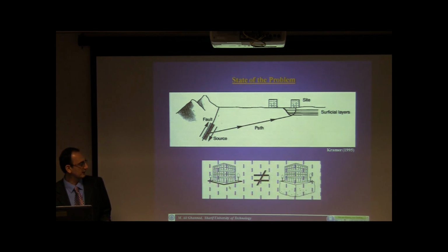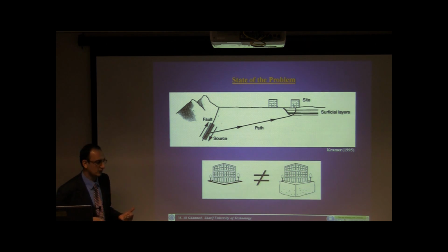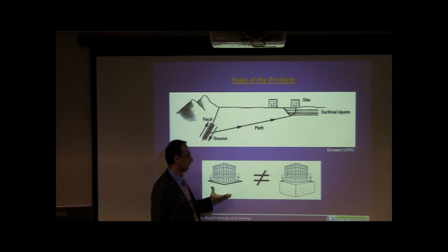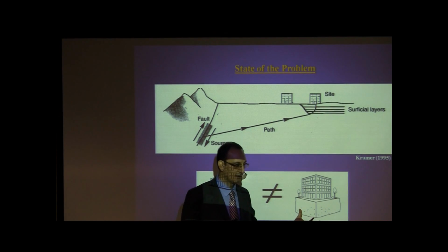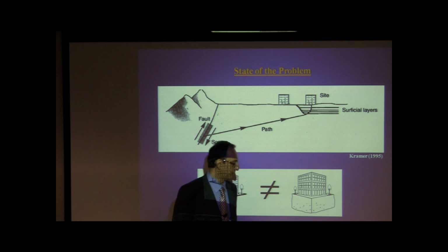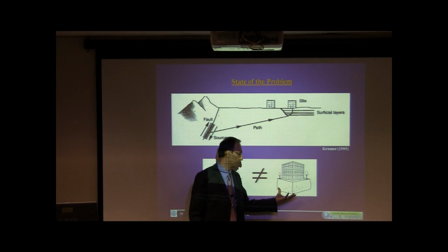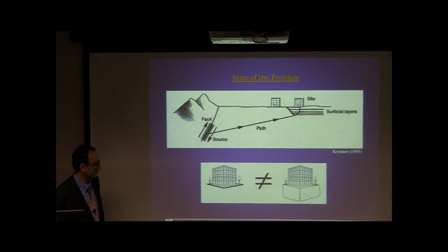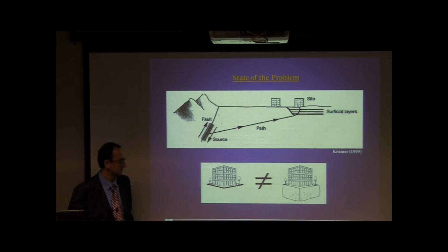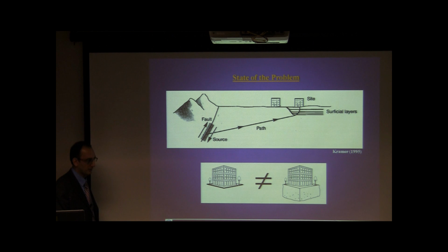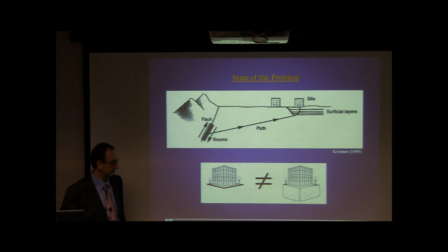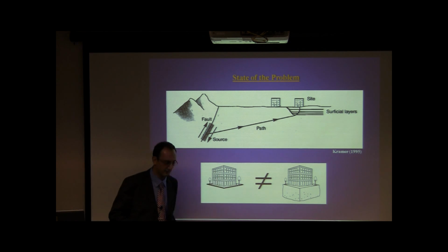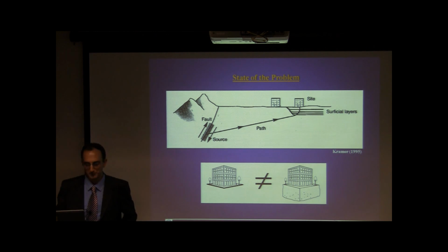And the main purpose is to say that fixed base structures built on rigid soil are not equivalent to those built on flexible soil. Of course, this is the real case, but for the results which come from models of structures on a rigid base, we have to think about the reliability of the results. I borrowed this figure from somewhere. It's not mine, but unfortunately I don't remember from where.